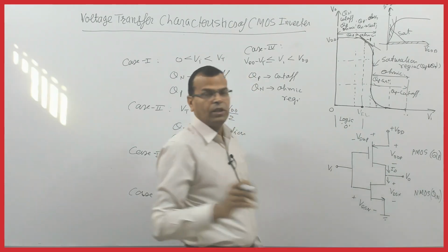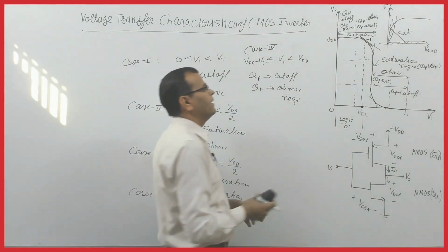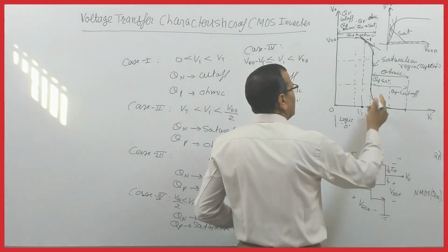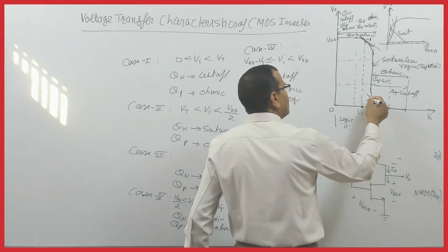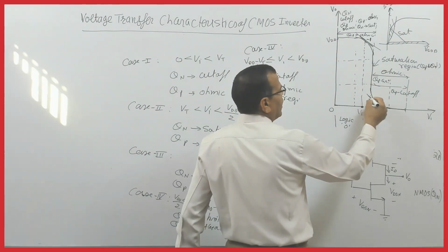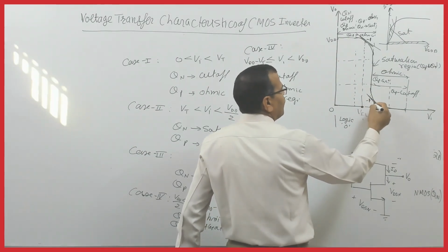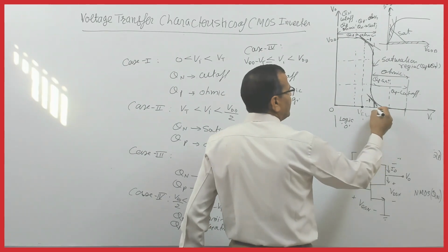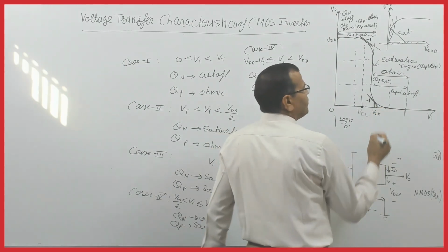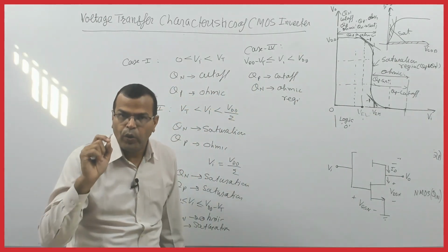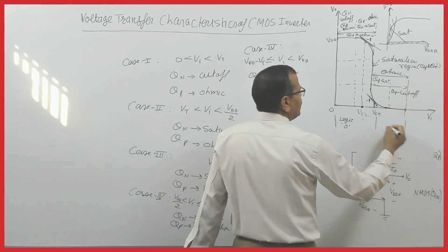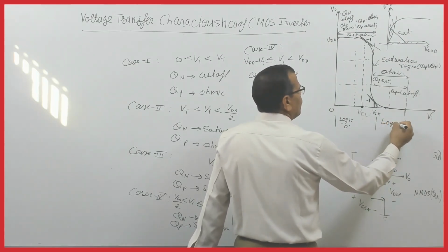For logic 0. Fine. Similarly, if you see the range of input voltage, you draw the characteristic and draw a line of slope -1 here. From here to here, this range, this is VIH. Remember, that is the lowest level of input voltage for logic 1. So from here to here, it is logic 1.